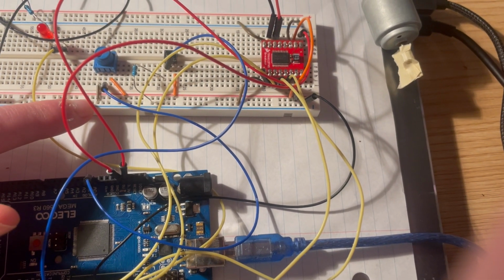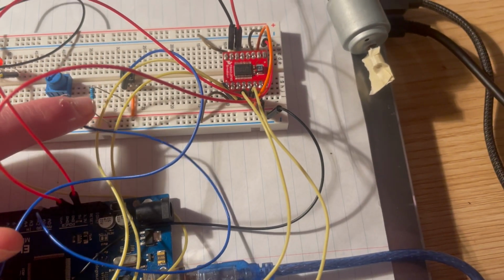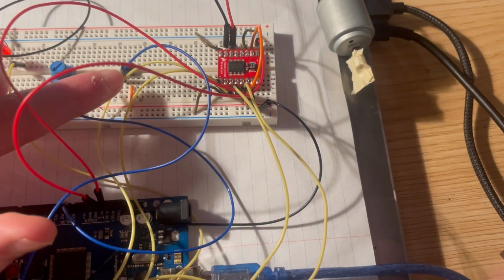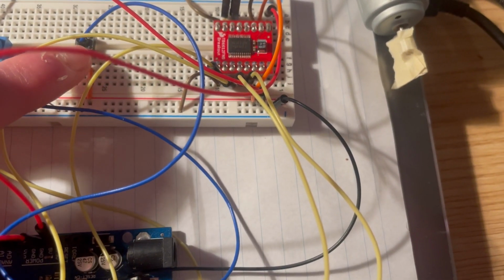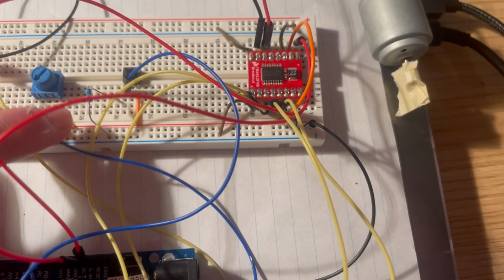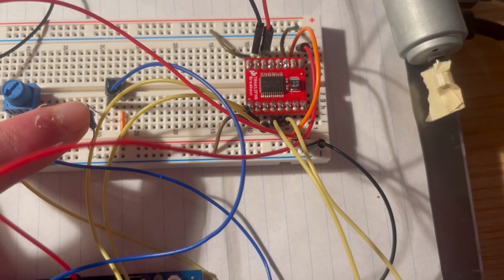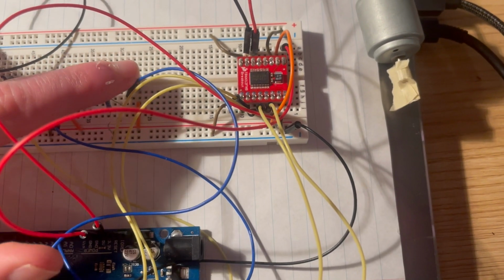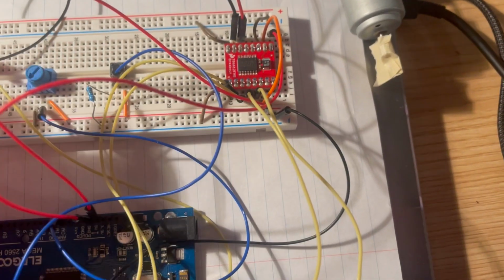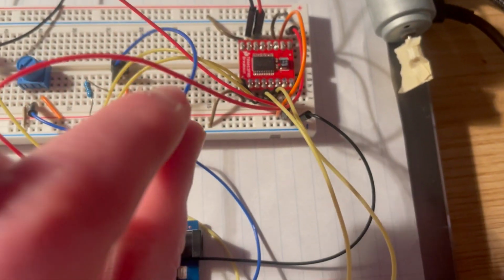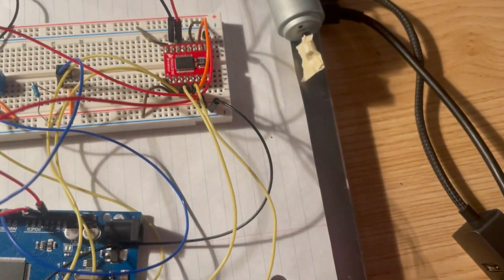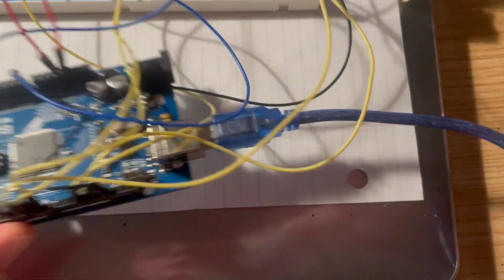And the potentiometer gets its current from the 3.3 volts from the board along this power cable and then is grounded. And then the button gets power from the 3.3 volt bar over here, and it goes into the push button, also called a momentary contact switch, and into ground with this 1000 ohm resistor. The way this works is that when the button is pressed, the circuit is completed, and that information is relayed to the Arduino through this blue cable into a digital input as well.